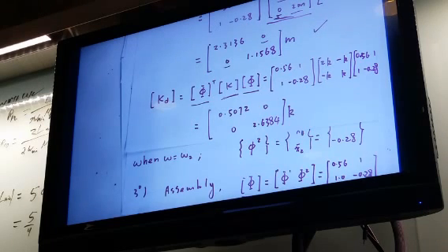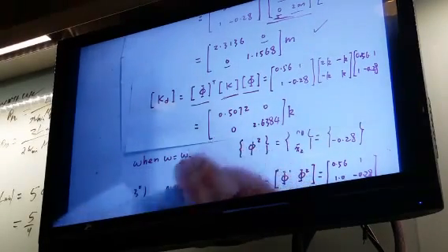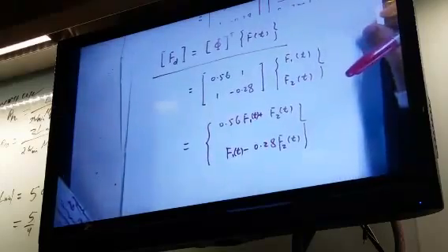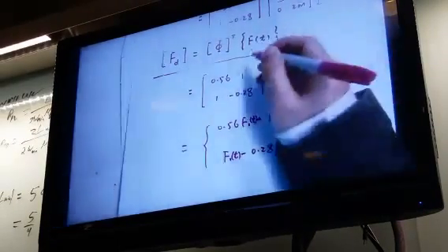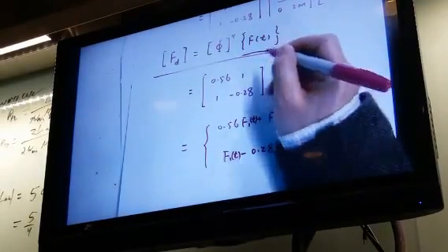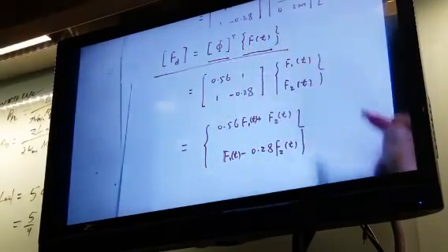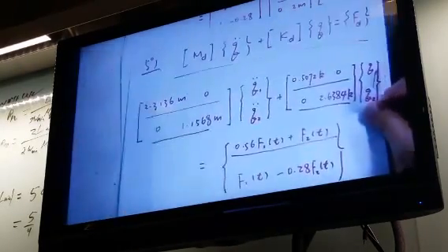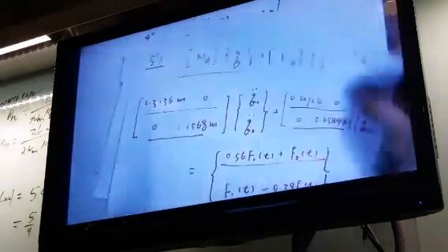So you transform M, K, and even F. If you have an external force, you can transform F. How do we transform F? This is the external force in Cartesian coordinate. This is the eigenvector matrix in normal coordinate. This eigenvector matrix is formed from the eigenfrequency calculation. And when you finish the transform, you can form the equation of motion in normal coordinate.